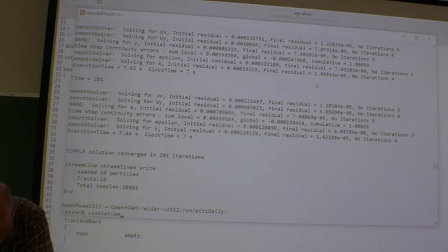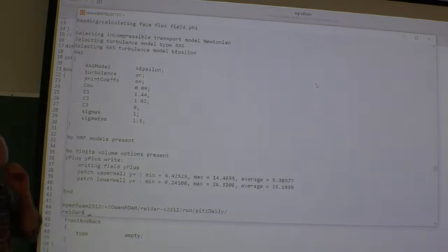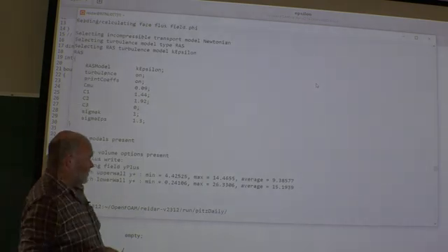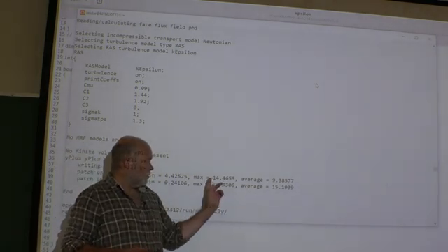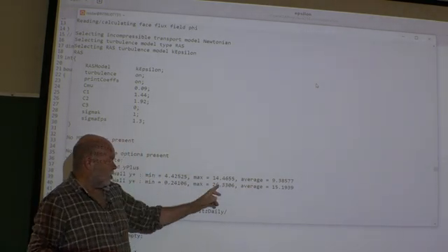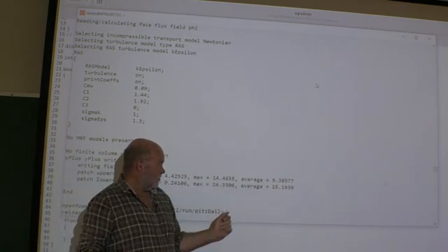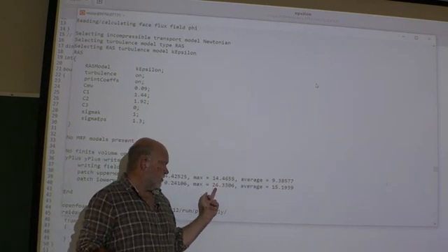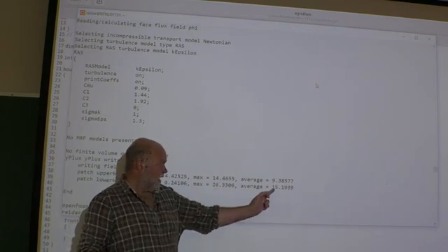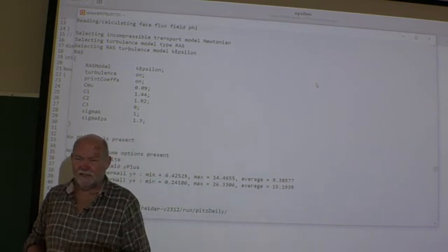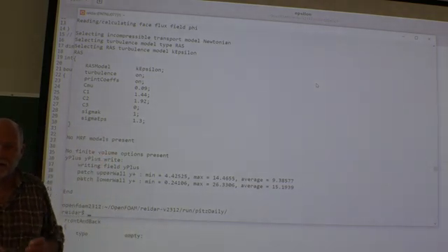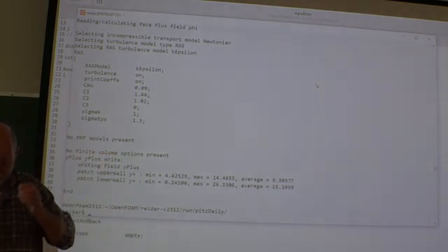And then let us do this y plus again. Thank you, that was a little bit better. Still, I don't like these numbers. Top wall 14 and 10. Lower wall close to 30, but below, and on average 15. That's just the value you don't want.